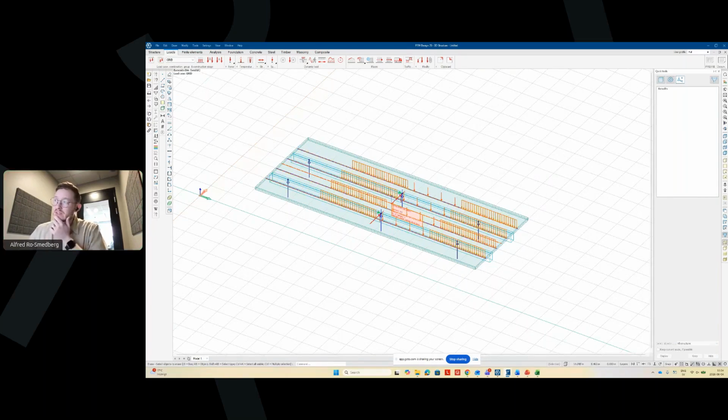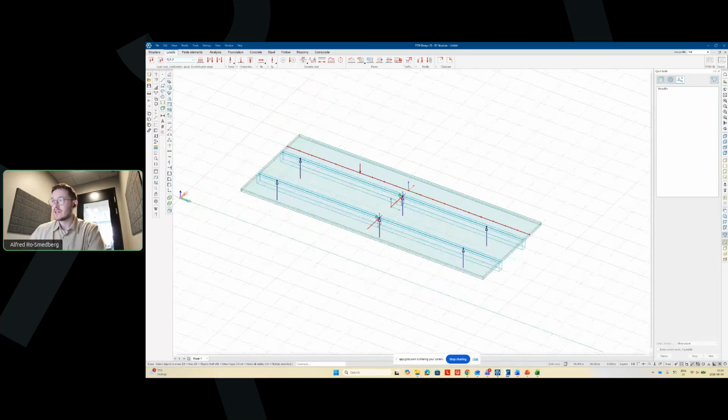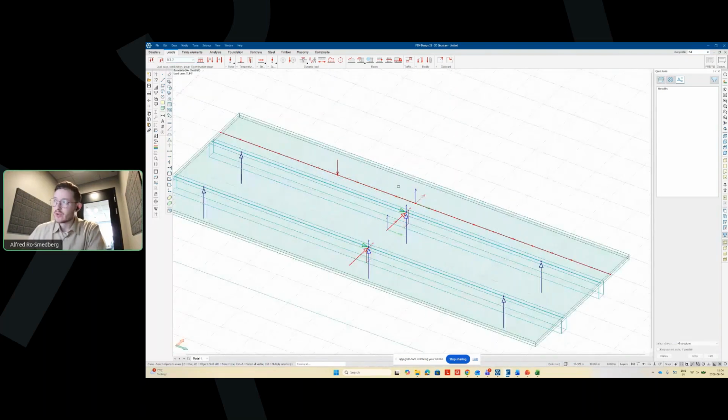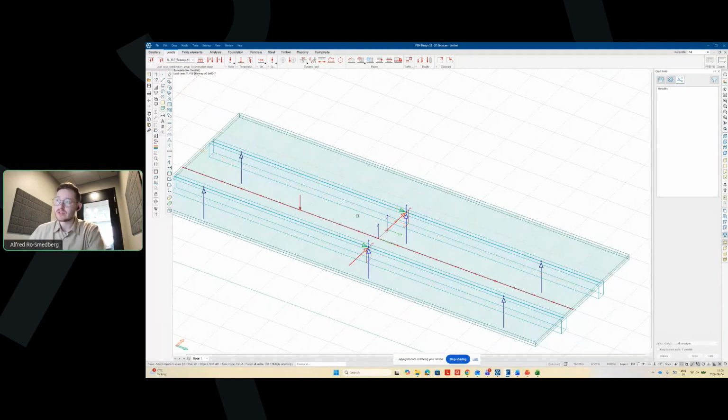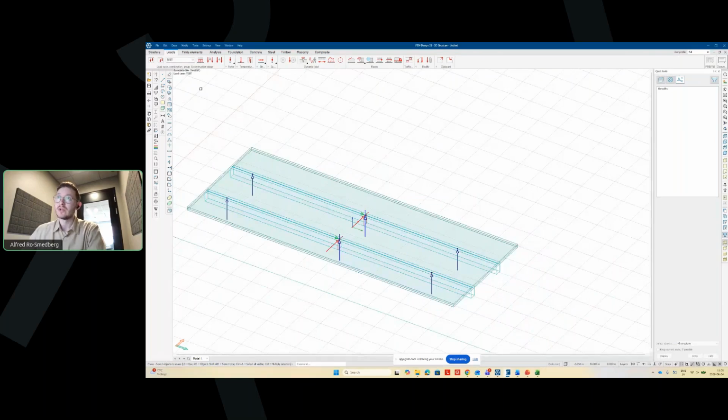You have to start by erasing the load in the corresponding load tab. And once you've done that, then you can go into these grid patterns that are generated, and you can erase those, because you cannot erase these patterns as long as you have a load in your model. So now we can see our load list is empty again.